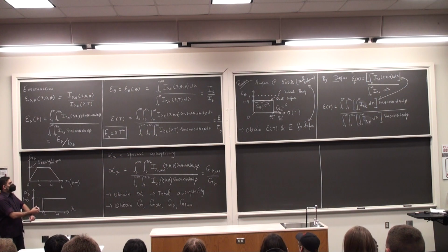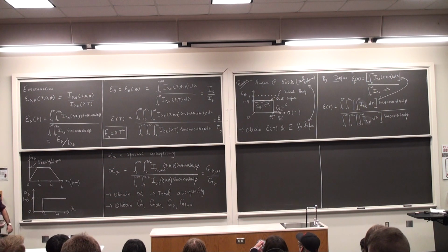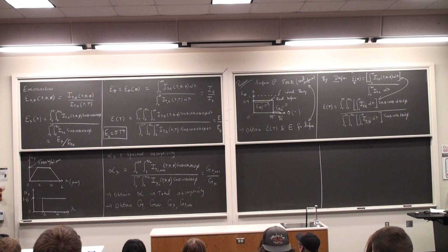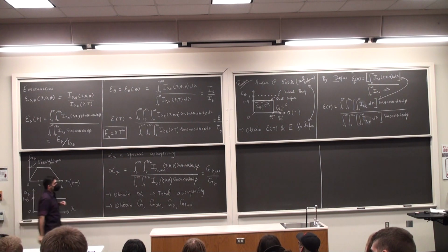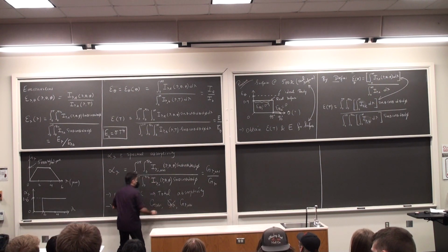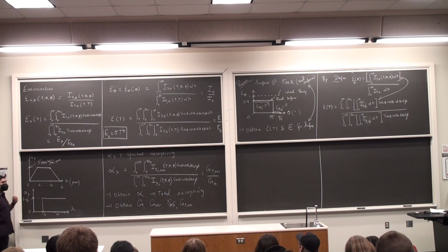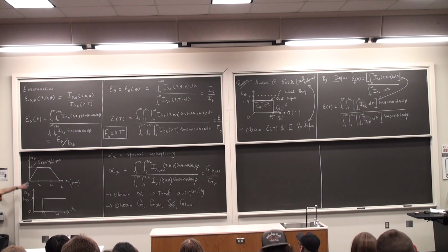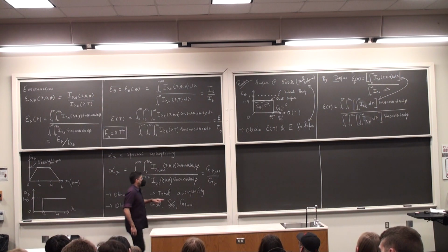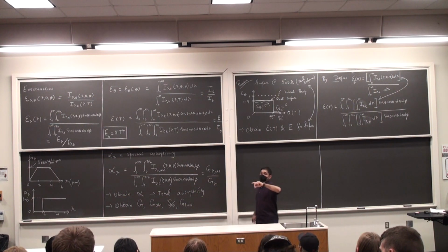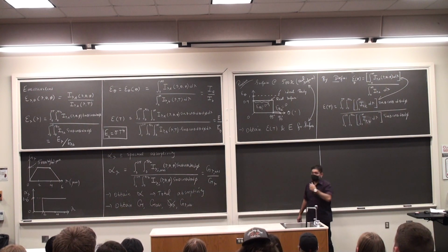Of course, G lambda and G lambda comma absorbed are at particular wavelengths which are already given to us. So I have G lambda, this is given to me, so I don't need to find it. I need to find G lambda comma absorbed using this plot and that plot. And something else that I'll also specify is that G, which is the total irradiation, is the integral of G lambda over all the wavelengths.